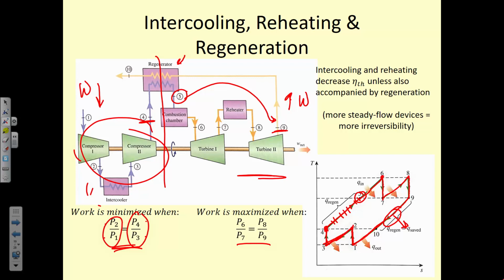And again, the greater the disparity between those 2 temperatures, the more worthwhile it is to put in a regenerator. If they're just a couple of degrees different, it's not going to be worthwhile. Okay, any other questions on this?